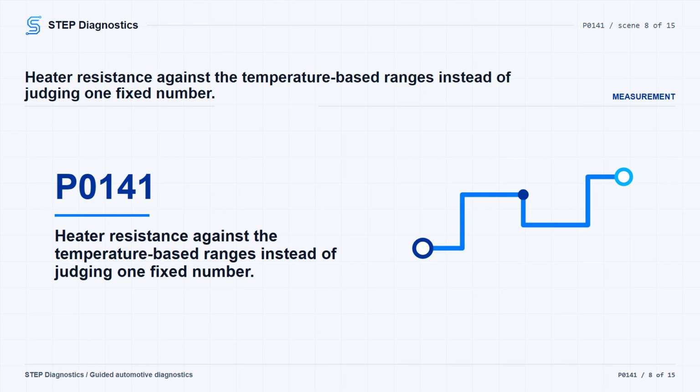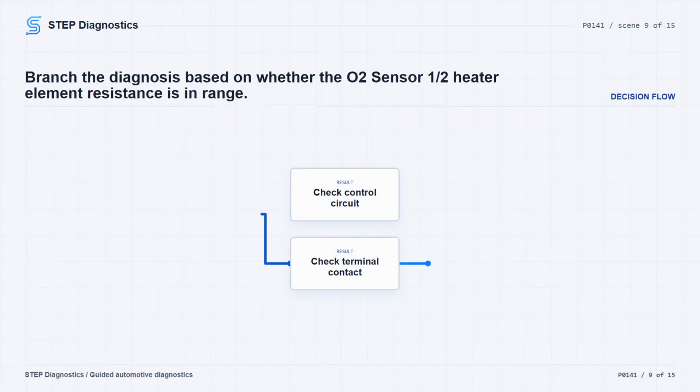At 0 degrees C, 32 degrees F, the range is 3.142 ohms. At 20 degrees C, 68 degrees F, the range is 3.344 ohms. At 100 degrees C, 212 degrees F, the range is 3.855 ohms. The maximum allowable resistance would be 12.5 ohms at 1000 degrees C.